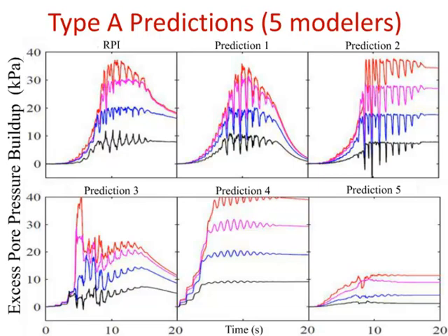This is work in progress, but what I can show you are some results that we obtained for a Type C prediction. We conducted the Type C prediction. This means a prediction that was conducted after model calibration using the open source code and the UCSD constitutive model. These are the recorded and computed accelerations along the central array from the input that is at the bottom all the way to the motion at 0.5 meter depth.